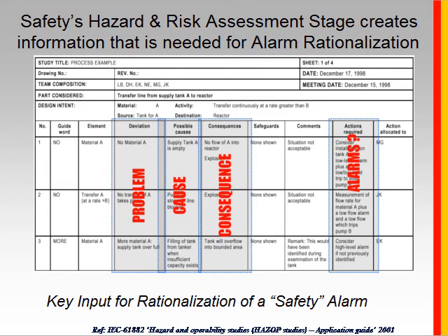They'll enable all those alarms, and then they'll set the limits not based on process dynamics, but just using a rule of thumb like let's set the high-high limit at 90% of engineering range, and the high limit at 80%, and the low at 10%, and the low-low at 20%. This way we end up with a whole bunch of alarms where the limits are not set based on true process conditions, and the alarms aren't actually necessary.